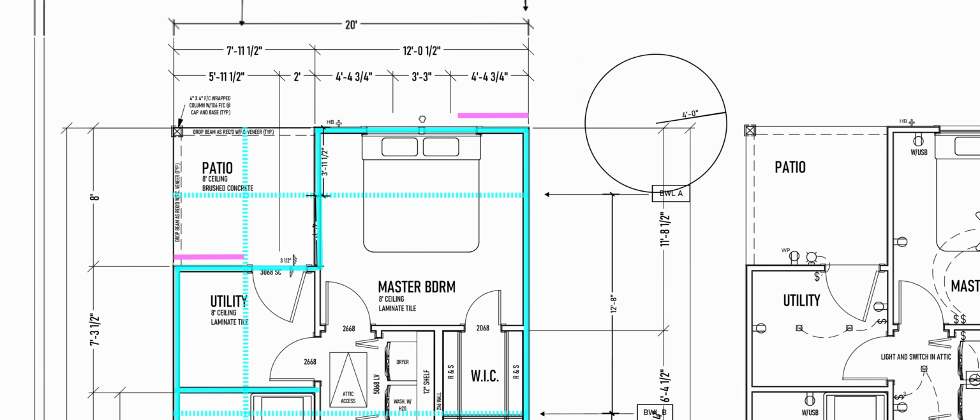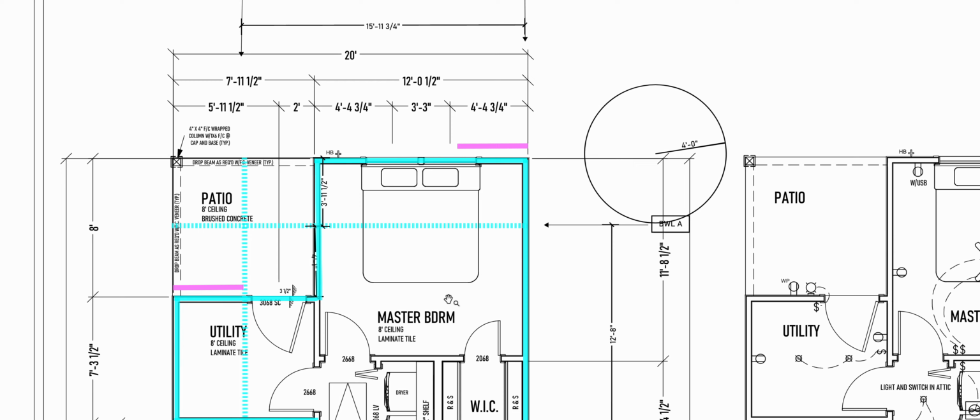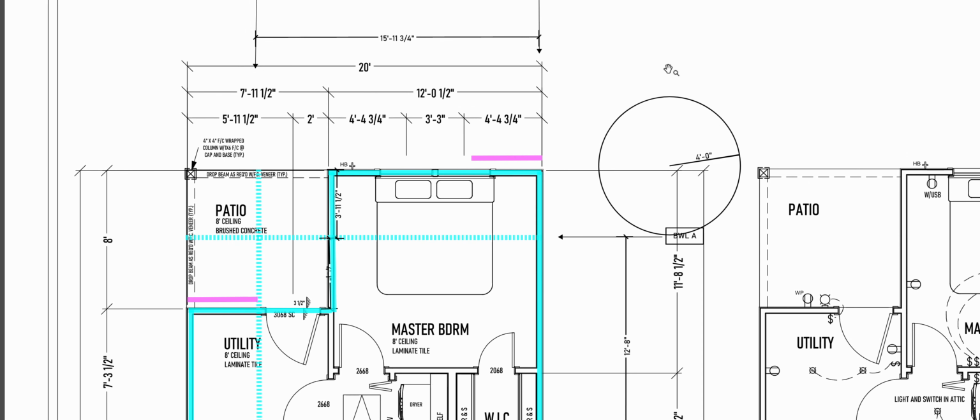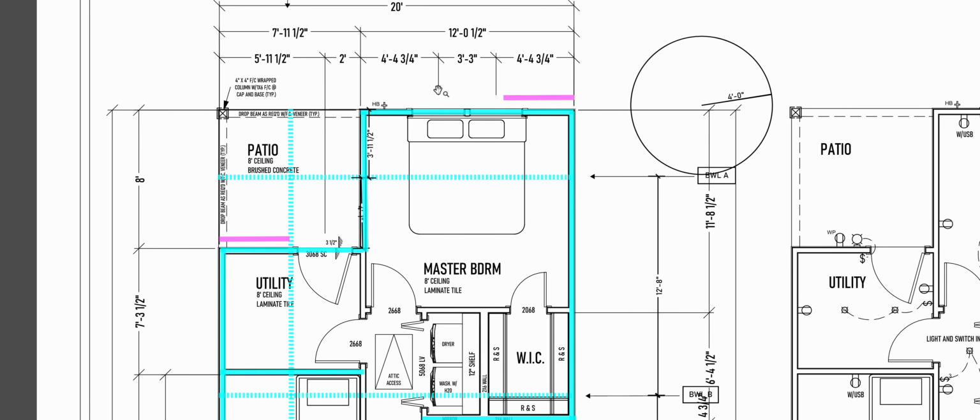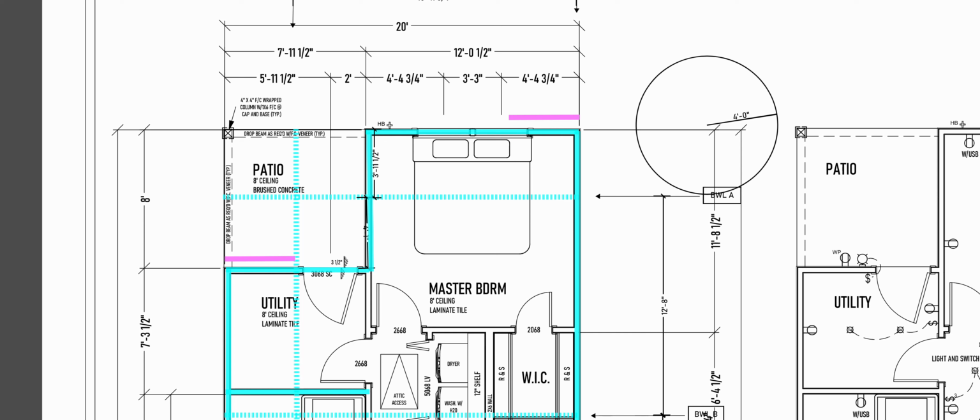And then these definitely aren't more than 20 feet apart because the whole building's 20 feet wide. So in terms of the left to right distance, I would approximate where I'm at here, and I would take that distance. I'm only concerned with the horizontal distance, 12 foot. So I'm good. It's the distance along my braced wall line here that I'm concerned with.